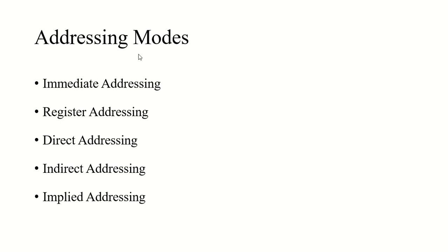And that instruction set determines what function that microprocessor can perform, right? So each instruction basically contains two parts. First part is opcode and second part is operand. So the opcode part of the instruction specifies the operation to be performed. What operation I want to perform is specified by opcode, and operand either provides the data or specifies the data,